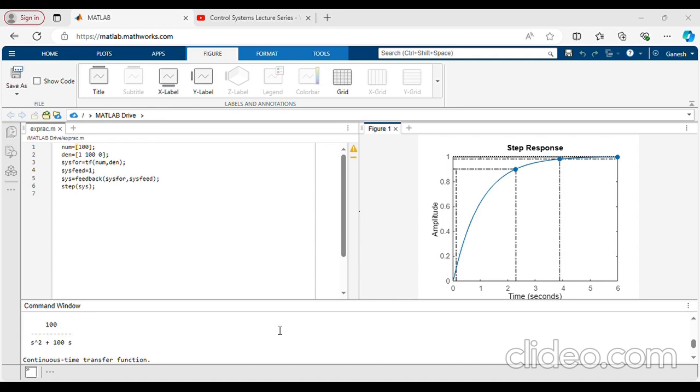That is why critically damped and overdamped systems are generally slower. So overdamped systems are slower, and the response is sluggish. That is why they find fewer applications. Where oscillations cannot be tolerated, in those applications only one can use overdamped systems. So that is why overdamped systems are seldom used. This point we have stressed in